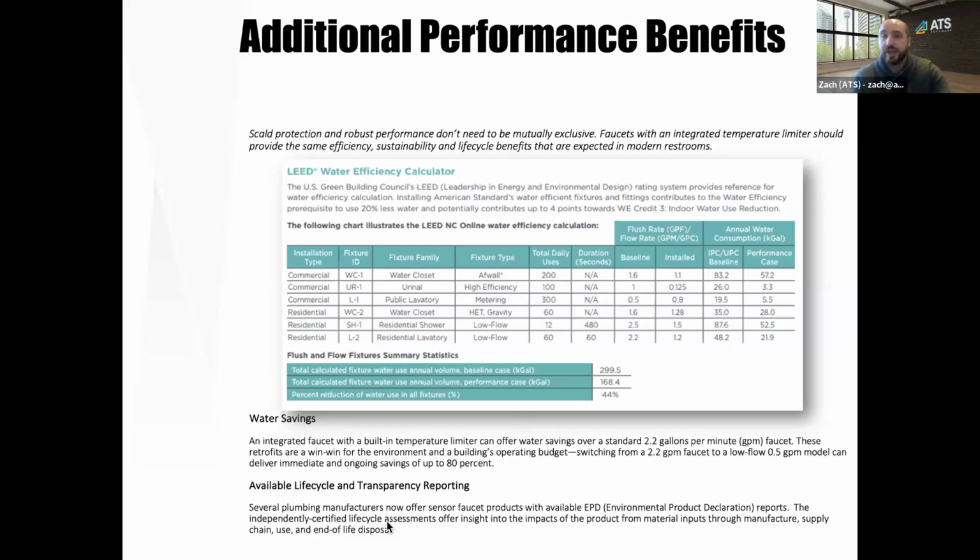Like you mentioned, there can be stagnant water inside your pipes, which decreases to a lower temperature. Now all of a sudden you have a breeding ground for bacteria. Wet, dark, colder environments, that's the breeding ground. So that's where the Legionella control comes in, which says you must be above 120, and then you have a separate code saying you must be below 120. So that's where the two-point